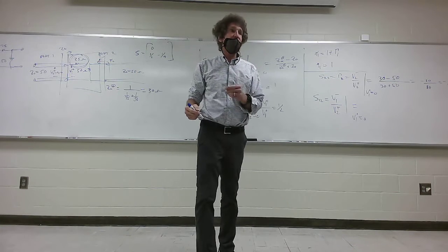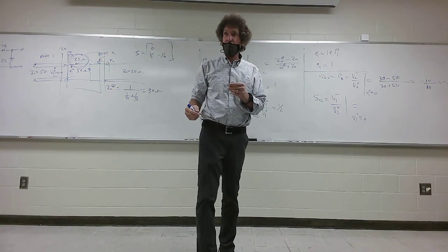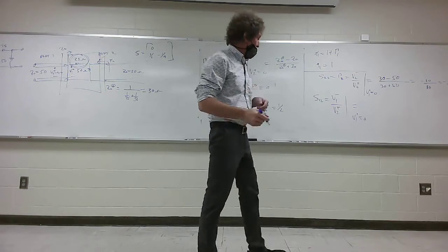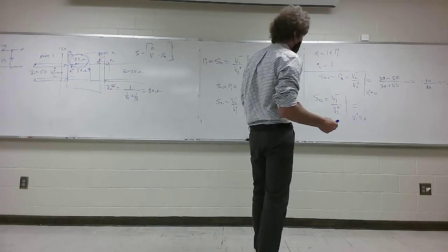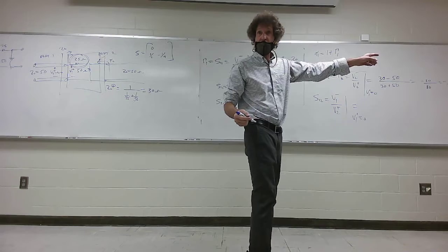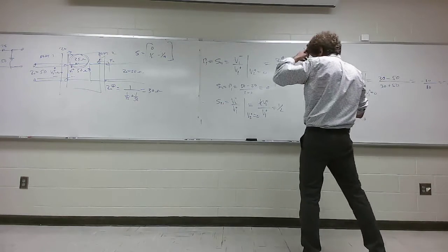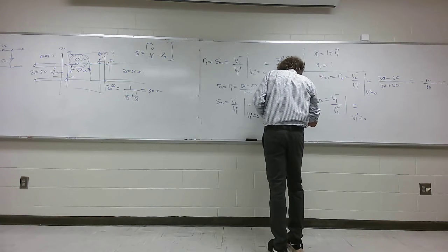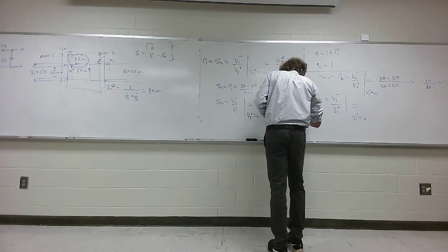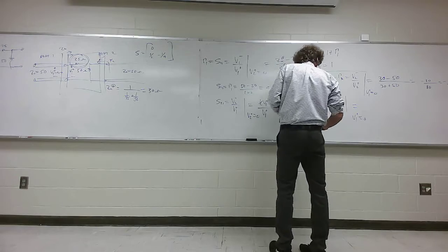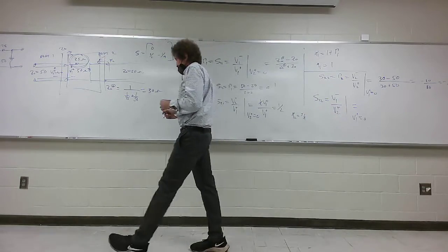1 plus what? The reflection coefficient on port 2, right? Which would be what? Reflection is minus 1, so it's 3/4. Do y'all agree with that? All right. So the transmission coefficient, and I'll put it here on port 2, is 3/4. Now we're going to go through calculating this.